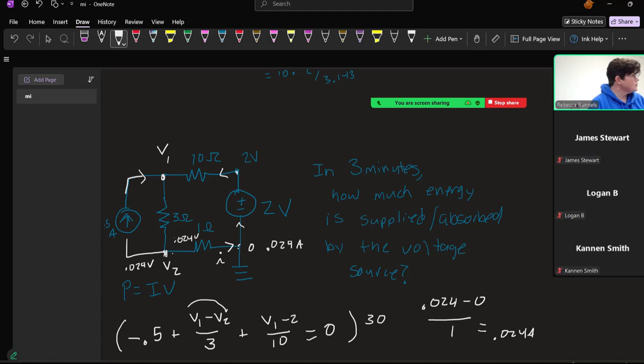All right. Okay, so because it very well could have turned out that the voltage source was absorbing power, in which case it would have definitely been coming from the current source. But it doesn't matter. We're measuring the voltage source, and the voltage source is going to tell us the power that it is either creating or absorbing, that the power that it's associated with.